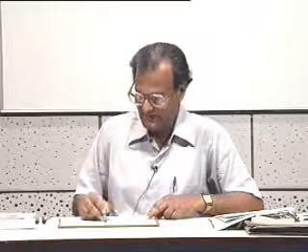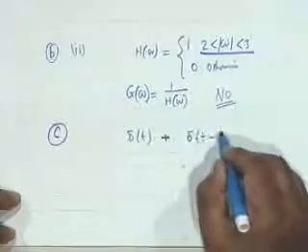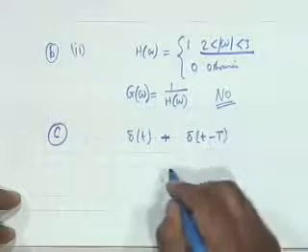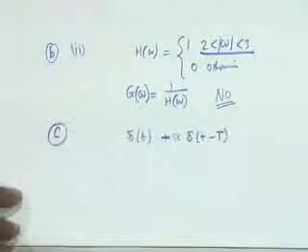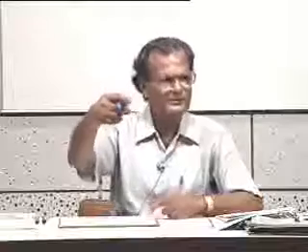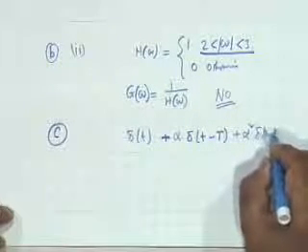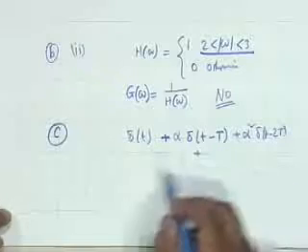So what you get is δ(t) as the input, then it's added to, let's say, δ(t − T) with some attenuation α, because the sound goes to the walls and then gets reflected. Then it gets α²δ(t − 2T), and so on and so forth.